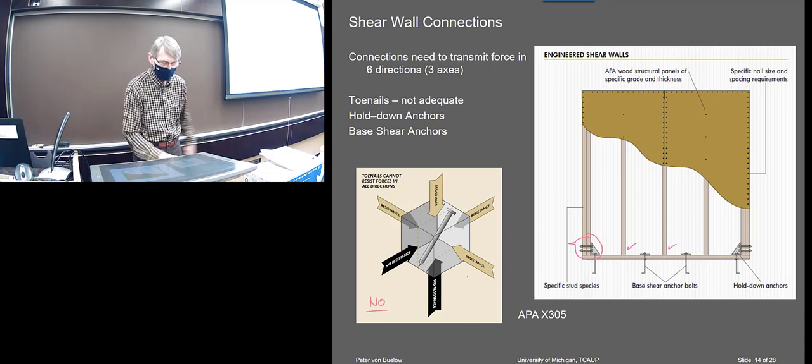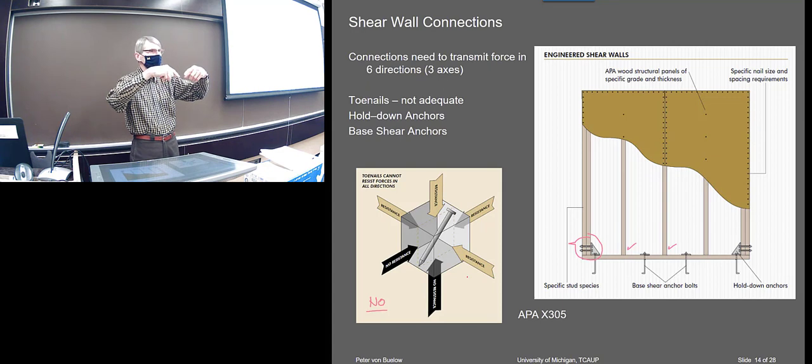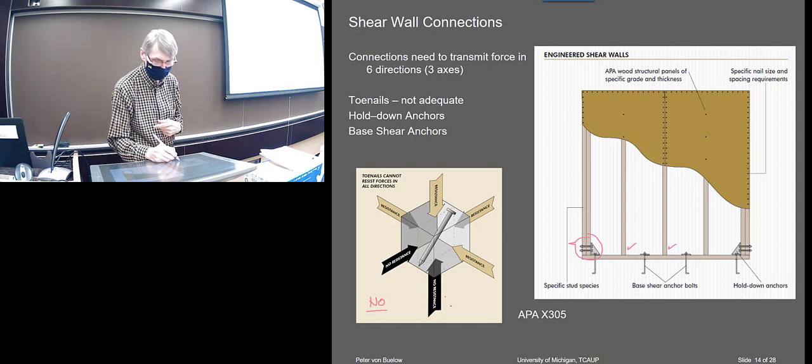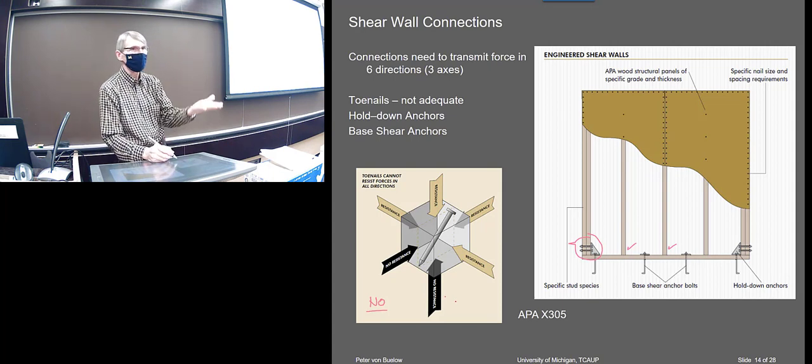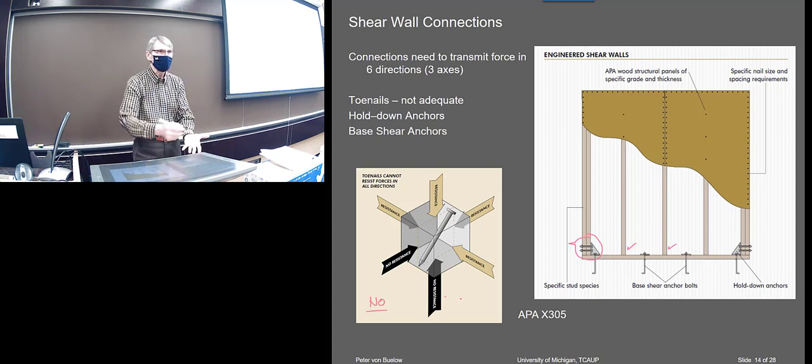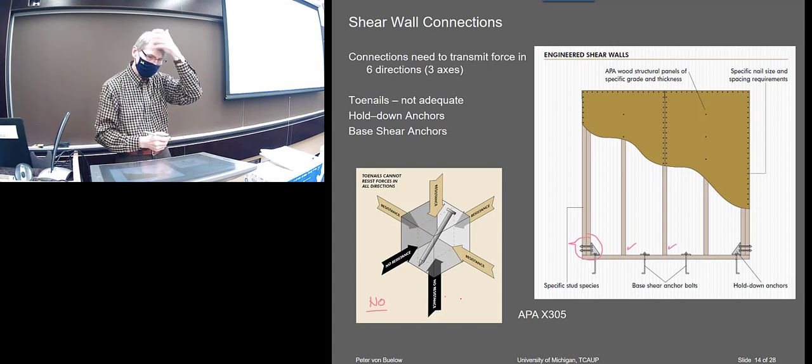you've got to put that nail in some direction. You can see if the force comes from this direction, or if it's an uplift force, which is very likely, that is the force that you're resisting primarily, because if it's a downward force, it's just pushing on it, then that's not a problem. But it's the uplift force that you really have to worry about.